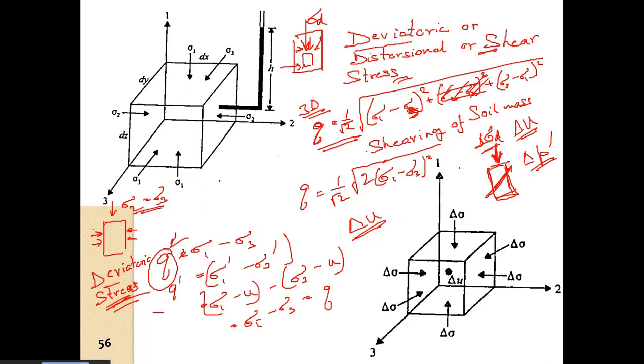All right. So during liquefaction, what happens? Delta U becomes such that we have sigma dash equal to 0, or actually P dash is equal to 0, but Q will remain there, because sigma 1 is there. So sigma 1 in that case will be equal to sigma D, whatever load we are applying. In that case, that soil will undergo shear failure, and it will deform. It will shear off, if that shearing or deviatoric stress is consistently being applied there. So that is a very important case.